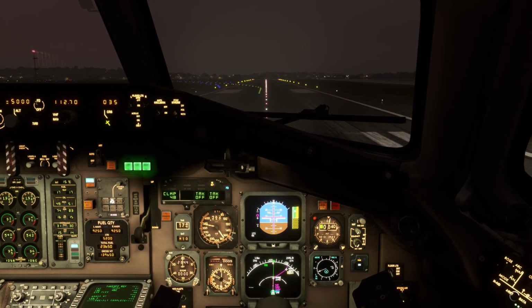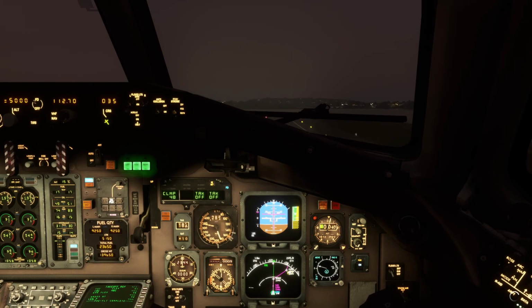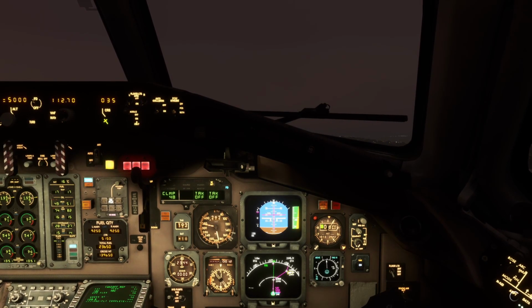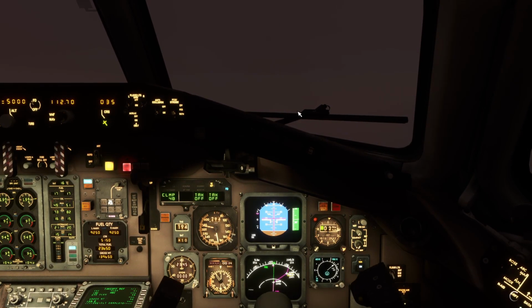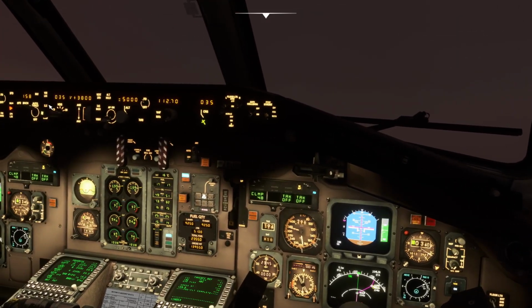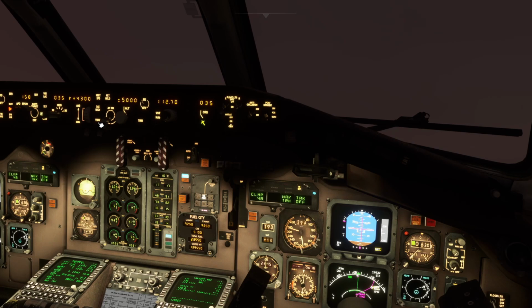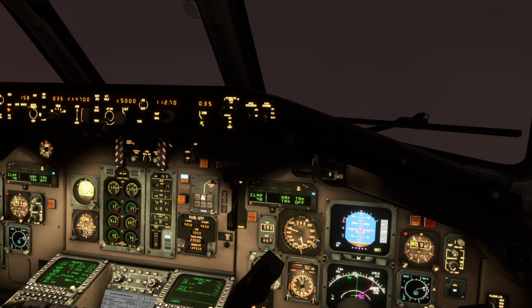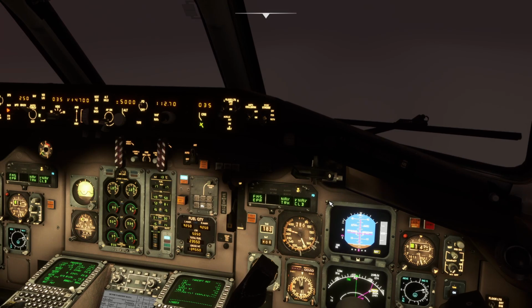Nice and gentle. Be a little easy with it. It's easy to tail strike it. Okay, positive rate of climb. We'll select gear up, and we'll follow the flight directors to pitch for V2 plus 10 or 15 or whatever. This is the radio altimeter here that you're seeing. Past 400 feet will engage nav, and past 1,000 feet will engage VNAV for an NADP2 departure. Well through that, we'll engage VNAV and select climb on the thrust rating system.